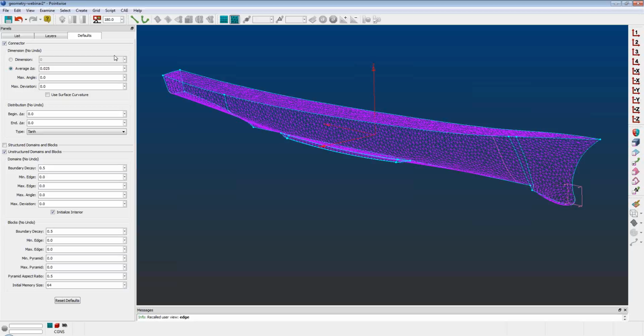First, is there a plan to include STEP to read the geometry in Pointwise? Right now, I think it reads only IGES. Rick, do you want to clarify that situation? Yeah, I'll talk about that. Currently in Pointwise version 16.04, which is our current release, the main way to import geometry is through IGES. We're currently working on the next version, which will come out sometime in 2011, that will incorporate native CAD readers, and that'll be part of the standard product, which is a little bit different than in Gridgen, where they were an add-on additional cost product.